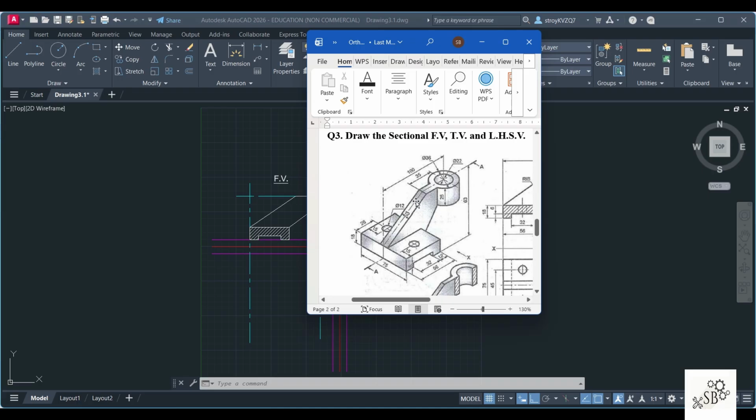Here this is a bent line, but actually from the top view you will see as a straight patch, and then you will see this rectangular box with 2 holes over here of diameter 12. Also there is a slot over here of 32 by 75. So this is a through and through slot that you will see. Now this length is 75 and this is 56.